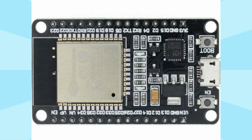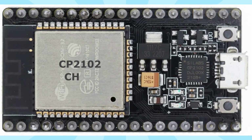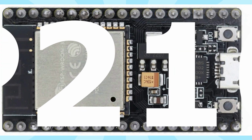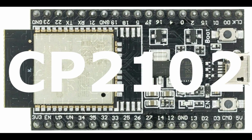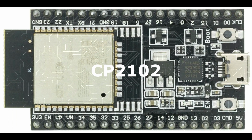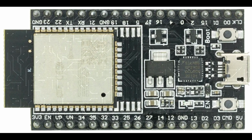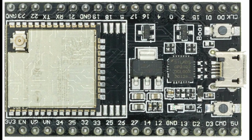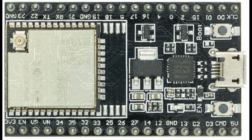ESP32 Devkit boards are sold with different programmers on board. These are such as CP2102, CH340G, and CH9102. I recommend using boards with CP2102 programmer. It does not require a separate driver to be installed on the computer. For other types of programmer, you need to download and install the driver. Installing the drivers will ensure that your computer recognizes the ESP32 Devkit when it is connected via USB.